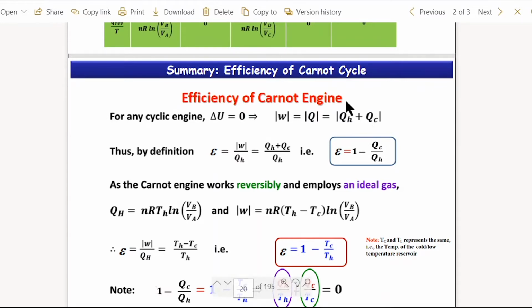So if I put it here, and write QC plus, I have to remember that this should be a negative sign because it's a dissipation. If I keep the plus sign, it is the total amount of heat absorbed plus the total amount of heat rejected. The total amount of heat rejected is actually minus, so we can always get back to the minus sign. Even if I write plus, and you understand it is actually minus, then it is okay. But if I write plus, then you have ambiguity. So I will correct that and make it minus.